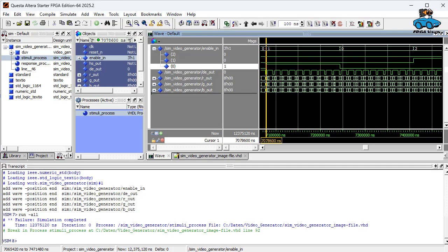And if we zoom in, we see here detail. And this is now the output of the test bench. So we don't get 6 separate images to save some simulation time. We have all 6 cases in one image, and with every switch of the input signal, the rectangle changes position and changes color, and after 6 switches, it goes back to the start position.